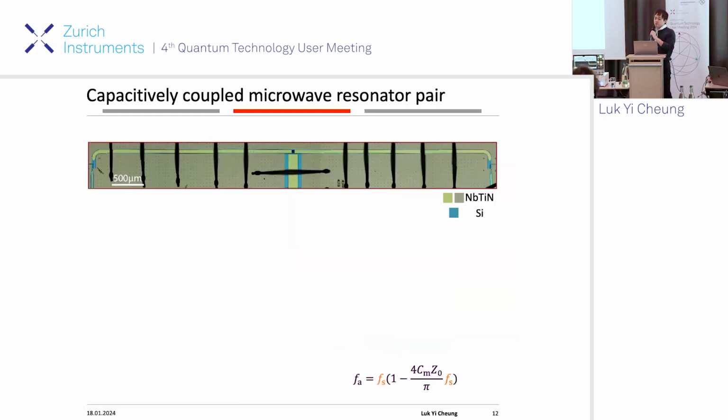And then I also come directly to the coupler. This is an optical image of the coupler. Let me break it down. So the horizontal transmission line, which you see there, that's the cavity coupler. That's 6 millimeter long. At the ends of the cavity coupler, we place our indium arsenide nanowires. As I already said, they are like 200 nanometer big.